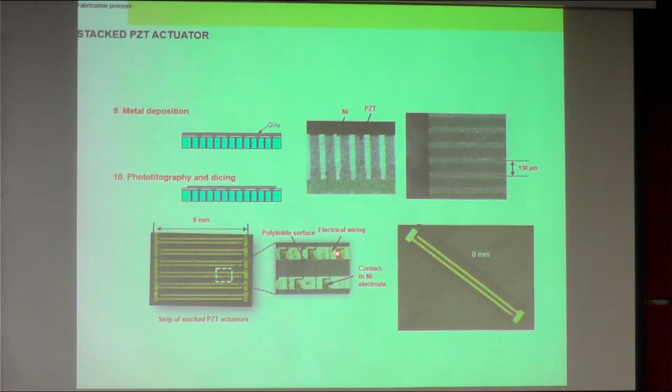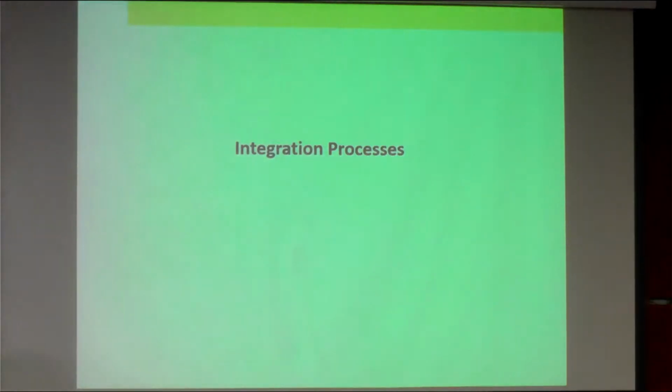The nickel electrode is connected on the left side and the top and the bottom in an interdigitated manner, so they will form a positive and negative electrode to the system. See here, the electrode is about 130 micron in terms of the pitch. So this needs to be integrated together between the stage and the piezoelectric actuator.